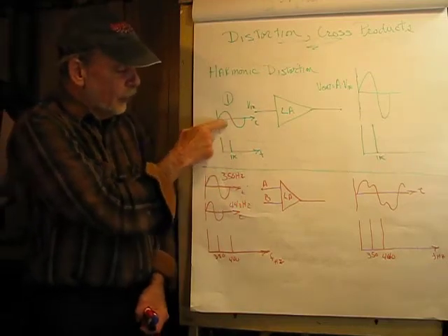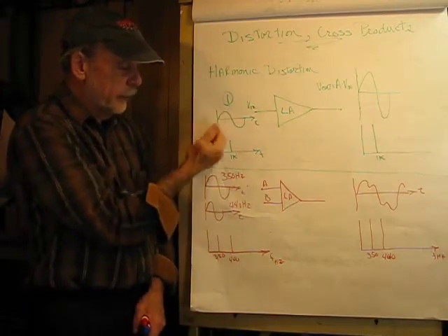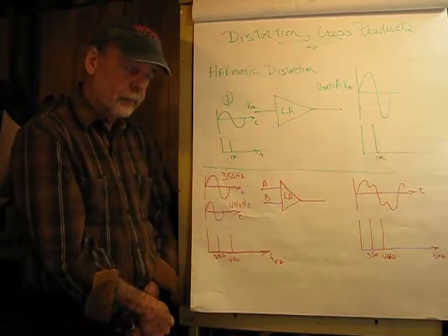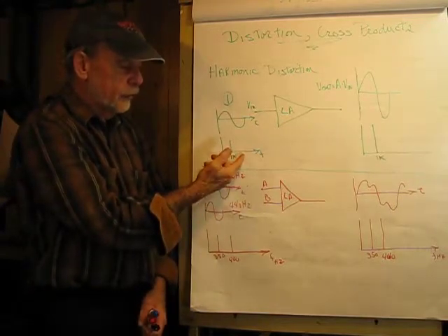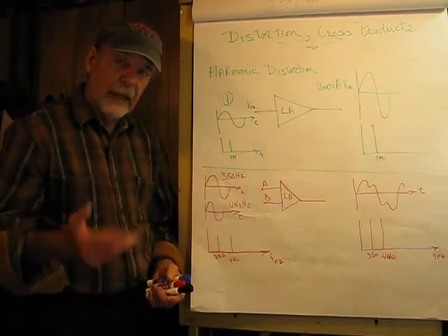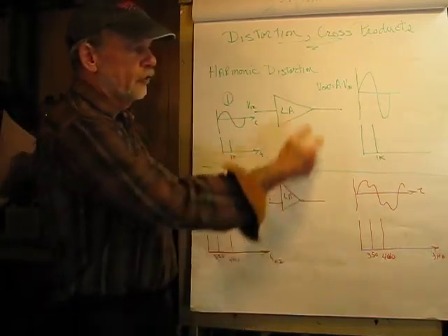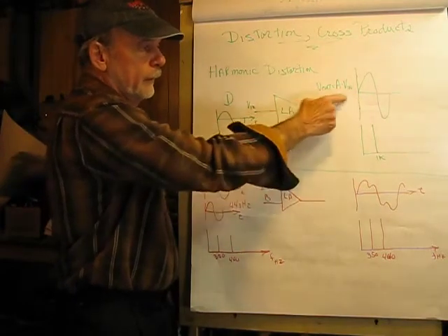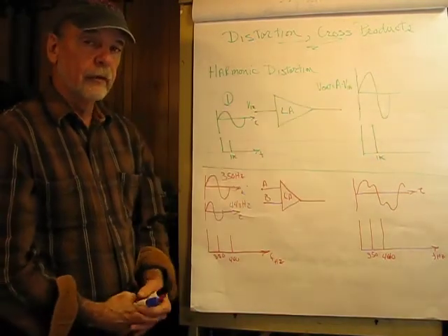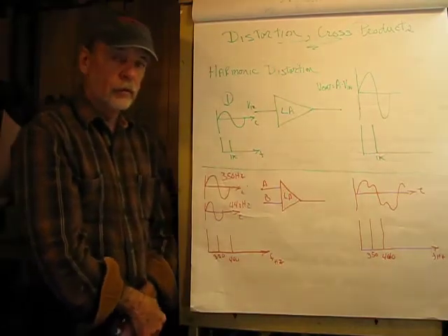So in both cases, what we can see is the amplitude of the signal, and in the time domain, if we get a complicated signal, it's very difficult to see different frequencies, and in the frequency domain, it's just about impossible to measure phase differences. So each domain has its positives and negatives. So we pass this through our linear amplifier, and as we expect, the output is going to be the gain times the input. So in the time domain, we see a larger amplitude sine wave, and in the frequency domain, what we see is a spectral spike at 1K, which is also larger.